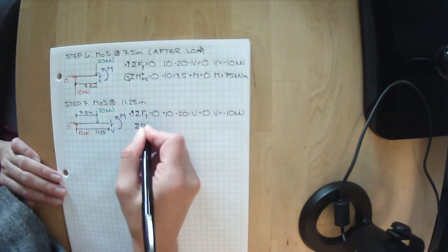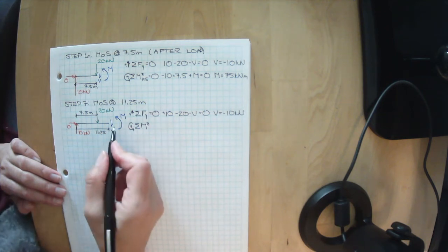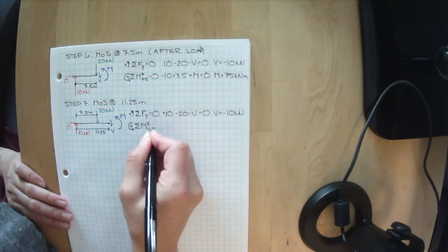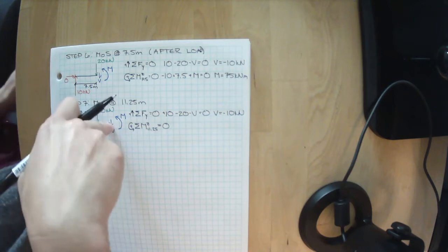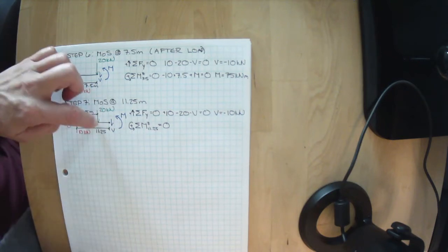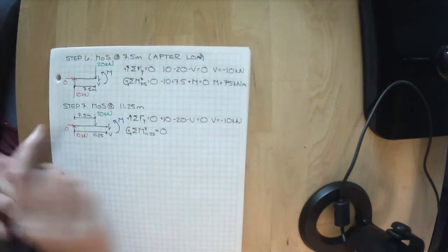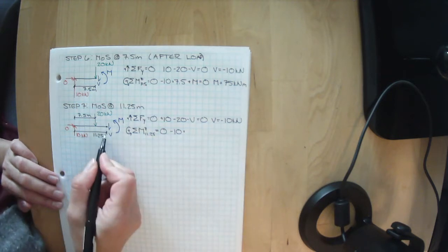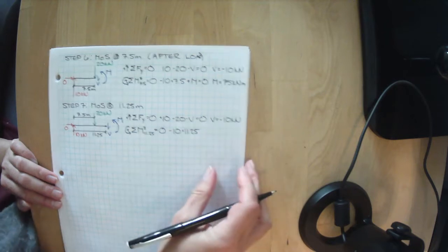Let's sum the moments about the z-axis, where everything in that direction is positive, and I'm going to pick the point where I made the cut, so 11.25 meters. So this is where my imaginary thumbtack is going. 10 kilonewtons is trying to spin it in that direction, which is negative. So minus 10 times, my 10 kilonewtons is 11.25 meters away.